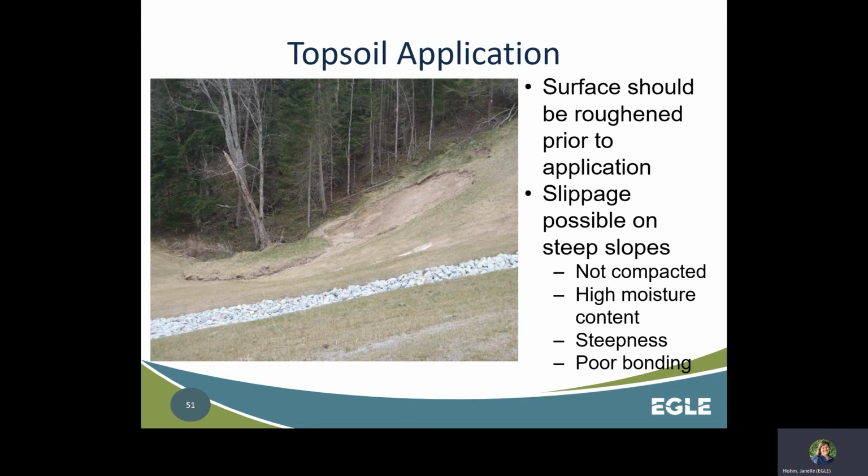Topsoil contains organic matter, which can hold and retain large amounts of water. By absorbing this water, the weight of the topsoil increases and it becomes more fluid. When possible, divert water away from steep slopes until vegetation is established.